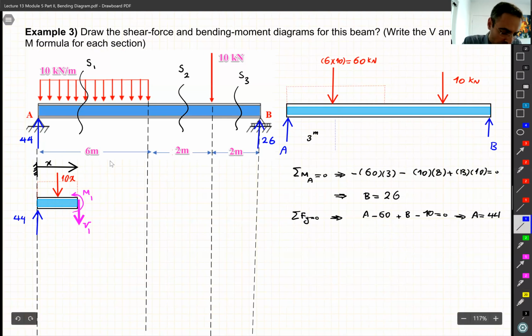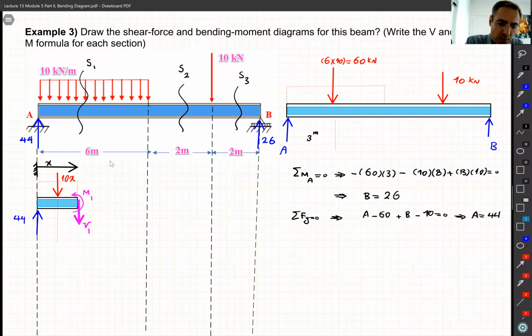And so what is this distance? Probably you can guess, because the whole thing is x, that thing is in the middle. So then this distance must be x divided by 2, right? Like over here. So our free body diagram is complete. If we draw a correct free body diagram, the rest is super, super easy. We just write down. So remember, this is for section 1.